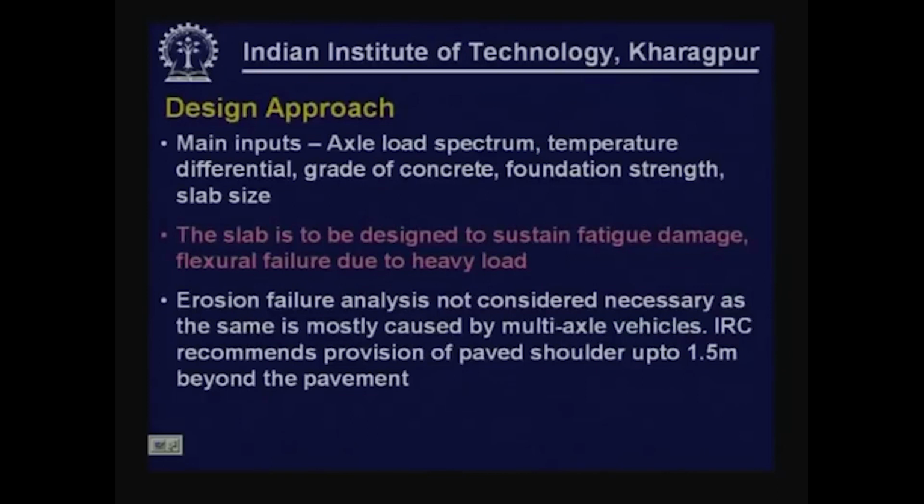The design approach consists of the main inputs. They will be the axial load spectrum. We have to have information on the axial load spectrum, the temperature differential, grade of concrete we are going to use, foundation strength, and the dimensions of the slab, which can be obtained after fixing the joint spacing.